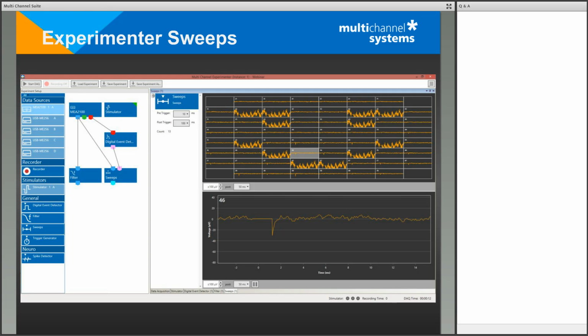And down here you see in the zoom channel, the trigger was a stimulation event, which happened at time point 0, so here, and you can see the small blanking period where all the electrodes were deactivated to avoid stimulation artifact, and this little residual artifact here when the recording electrodes come back online, just something short of 2 milliseconds after the actual stimulation. So that would be the standard tool if you work with evoked activity. Then as an output, you get these sweeps, which can also then in the end be connected to the recorder.